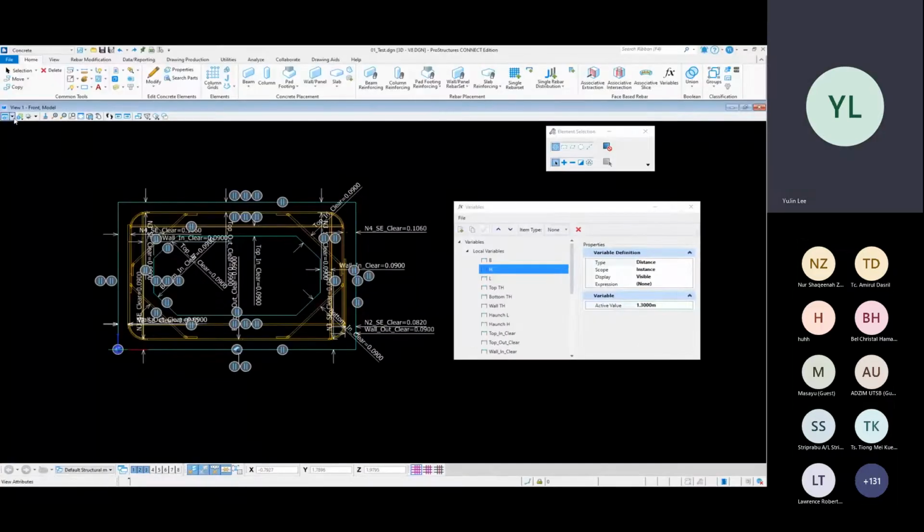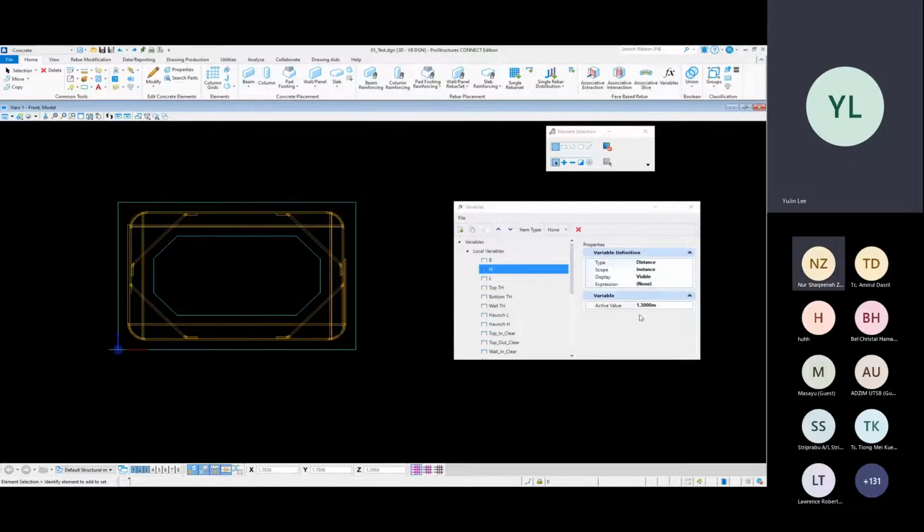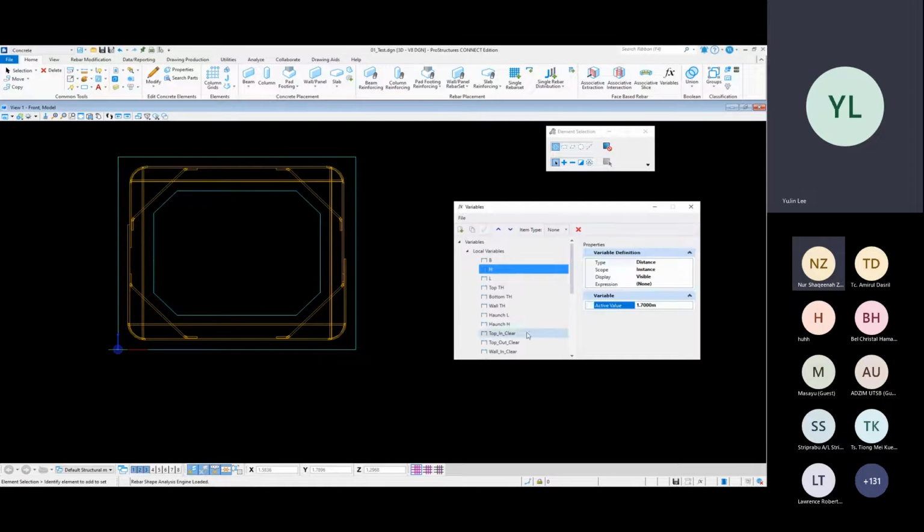And also you can place the parametric custom rebar to a custom element using the functional component. I generated some guidelines for the rebar shape using functional components, and the guidelines are connected with the custom solid using constraints and dimensions. Those rebar geometries are adjusted based on the custom solid dimensions. Also, you are able to control rebar size and spacing anytime.